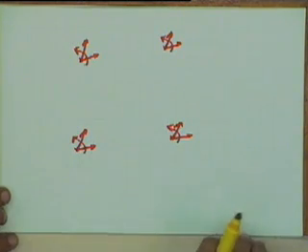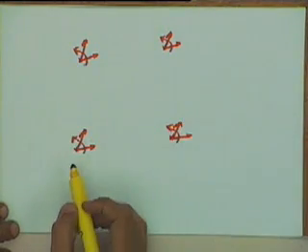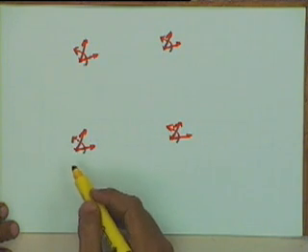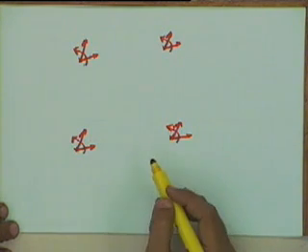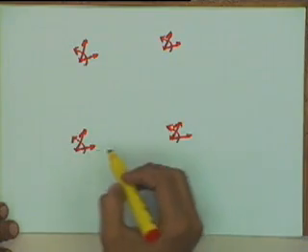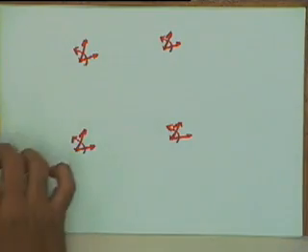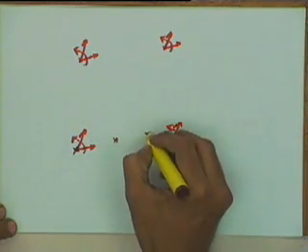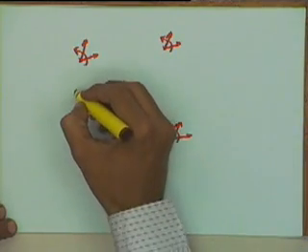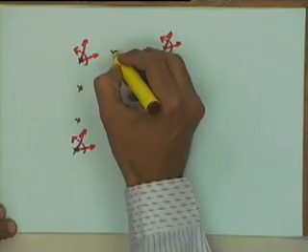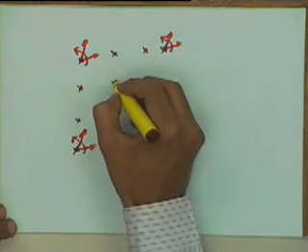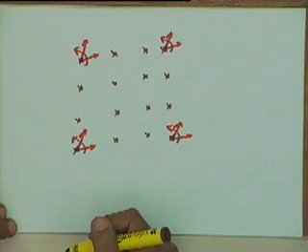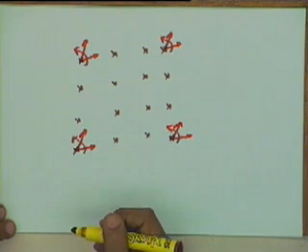But generally it is difficult to give input in the form of twist vectors or tangents. Instead, we sometimes prefer to give input as points. So if you want to give the input as, let us say, 16 points on the surface, then we can give an array of 16 points at specified values of the parameters u and v.